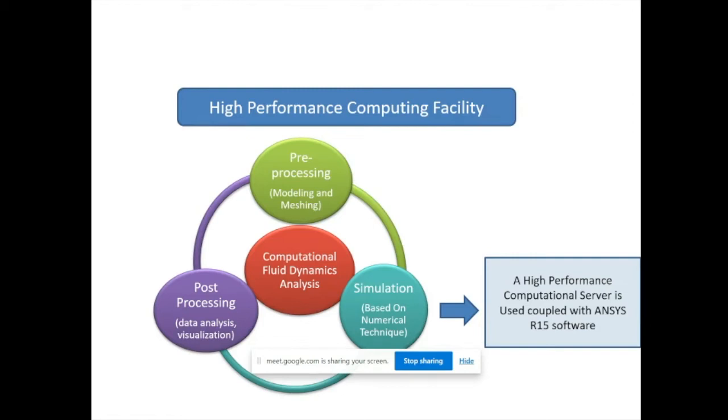And with my experience, I can say that for transient analysis, suppose we have 100 cores of computational facility, it takes 10 days to do the simulation at one operating point. So that kind of simulation power is required in the case of transient analysis. That's why for transient analysis we should have a high performance computational facility. Then only we go for a transient simulation.